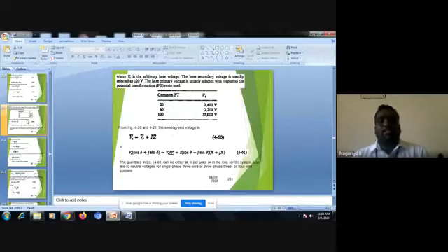When a potential transformer is there, depending on that you go for the base voltage. That base voltage has another name, arbitrary base voltage. So this base primary voltage is usually selected with respect to the potential transformer ratio used.